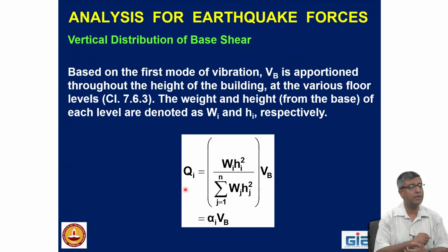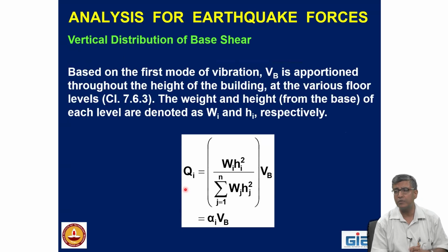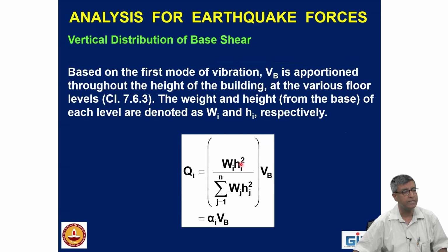Now, once you know the base shear, then you have to distribute that over the height of the building. And that distribution is done considering the first mode of vibration, which is parabolic in nature for a regular building. And this is the way the forces are calculated, where h is the height of a level from the top of the foundation.